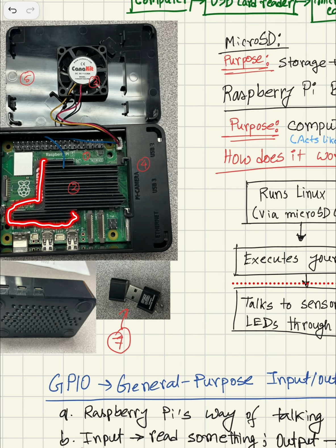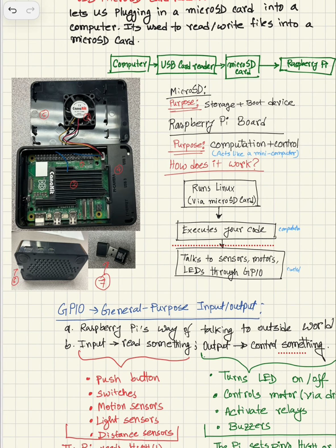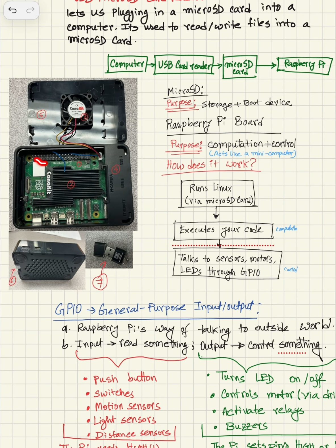We don't want the heat to accumulate, and that's why we use number 2, which is a heat sink. It spreads the heat so that it's not concentrated in a particular location, which can damage the chip. It spreads the heat, and this fan is used to dissipate the heat outside. So basically the cooling assembly is used to help us run the Pi for a longer time.